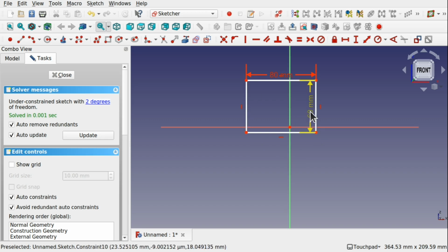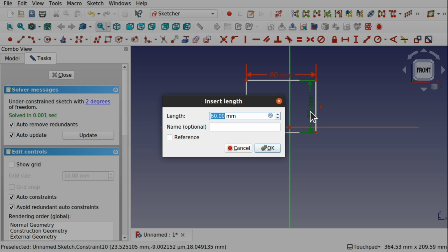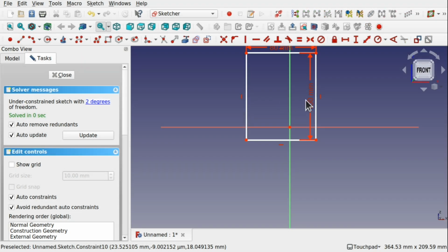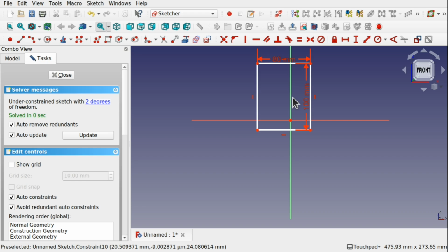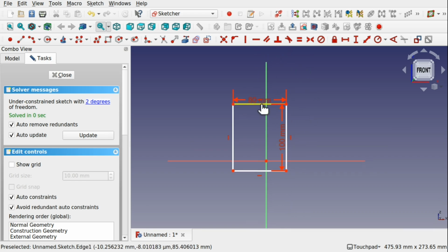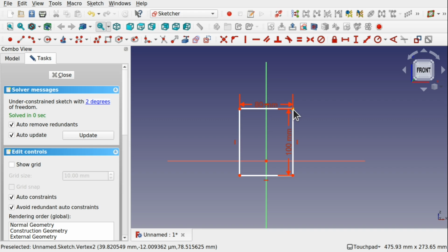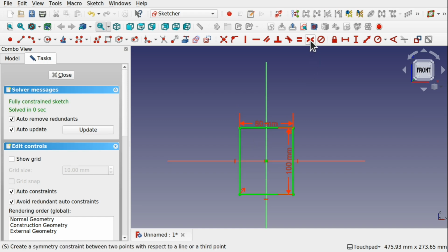As a matter of fact, let's go a bit higher. So something like 100 mil in height. So we've got that square or rectangle there. We can position this. I'm going to make this positioned center across here. So I've selected this point, and I'm going to make it symmetry to the center point. So the ones on the corner, and last of all the one that I want to make it symmetrical to, and use the symmetry constraint, and that's constrained it there.